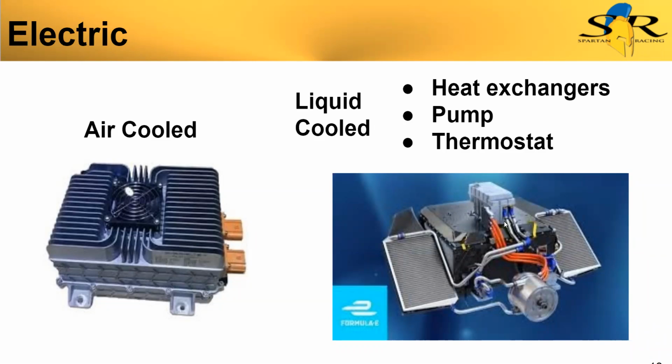And then another way to do it is to run the components in parallel. So there you have a lower system pressure overall, but you need a higher flow pump to handle that, even though there's lower pressure. So there's a few different ways to deal with that.